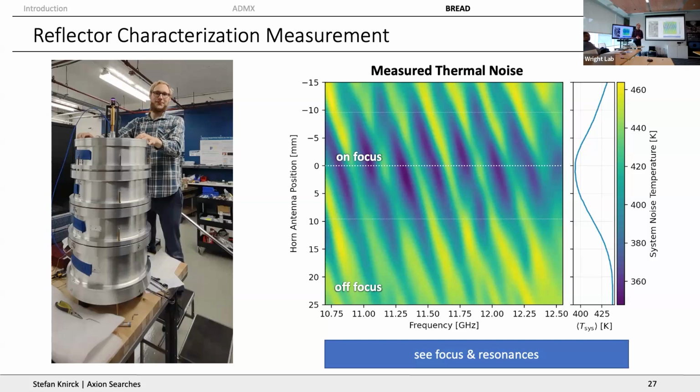What resonance are you talking about here? I thought this was non-resonant. I mean, you just mean the net of these standing waves is like one, right? So it's not really resonant, but if there is a small reflection coefficient on your antenna, it still means that part of the coherent photon wave function is being reflected, and in the worst case can cancel out some of your signal. It's like a standing wave between the antenna and the... Exactly. It's a mismatch, right? And every antenna has a mismatch. So it's important to take it into account.